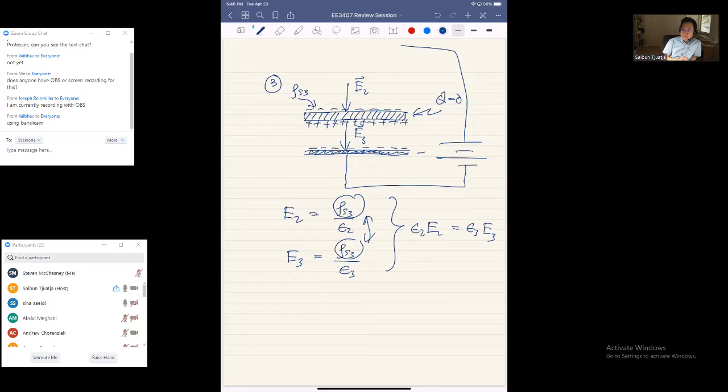Any questions so far? So now I have how many? What's the fourth one? The fourth boundary condition is easy, the same. I have, again, a conductor here, right? Because it's negatively charged, the field will be going in, E3, at this boundary. At this boundary, it's normal to the surface. And E3 is simply equal to whatever charge we had earlier, rho S over epsilon 3.